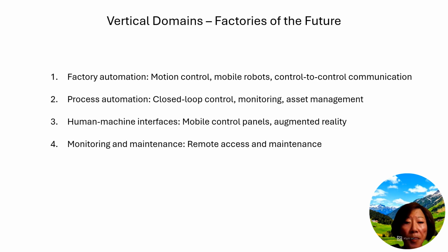To support such demanding requirements, 5G employs a combination of radio and network technologies. For ultra-low latency applications, the system uses techniques like grant-free uplink transmission and mini-slots, which allow for very short transmission times. Deterministic latency is achieved through careful scheduling and resource reservation, often involving techniques like semi-persistent scheduling. That's one of the techniques.